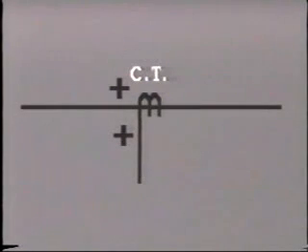On schematic diagrams, the CT is often shown like this. The plus sign indicates where the primary current flows in and where the secondary current flows out. You will also see CT polarity markings shown as X's, dots, or even squares. This identification enables us to connect the secondary windings to the relays in the correct relationship.